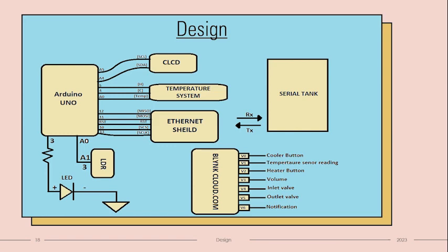Next is the design of the Arduino project. Before knowing the design, we have to be very familiar with the inputs and outputs. For example, when an LED is blinking, it is giving an output by switching on and off, so the LED is an output device. The LDR senses light by taking resistance, so it is an input device. Whenever we write the program, we have to define the input and output devices very clearly so that we do not get any glitches in the code.